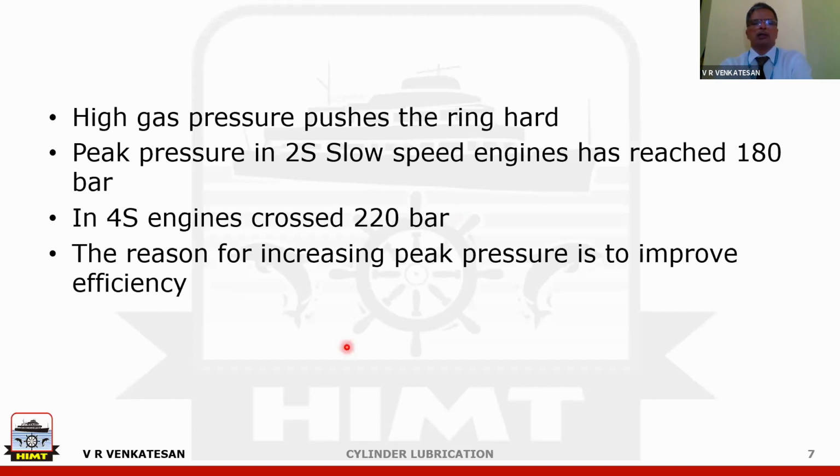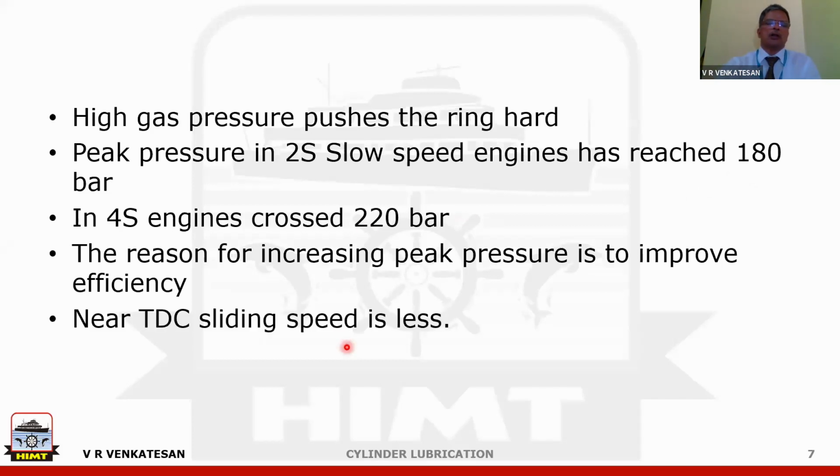The limitation is the ability of all your engine components to take the pressure. So the problem developing for your cylinder lubrication is that this value is becoming high. The force with which the piston ring is being pressed is becoming more and more.